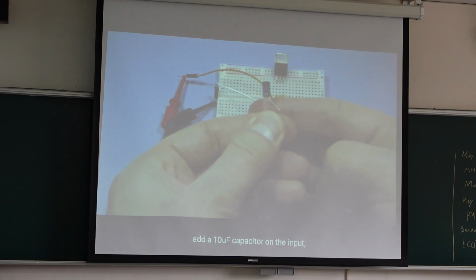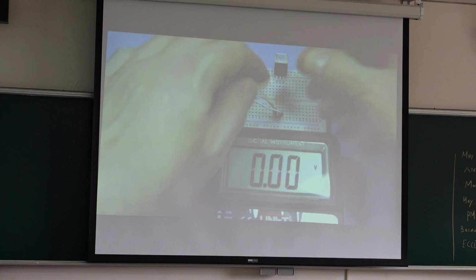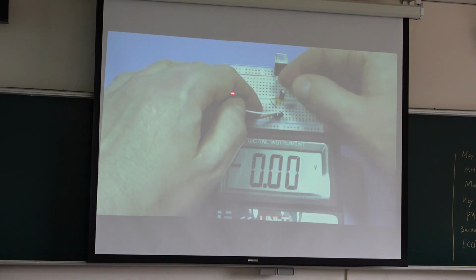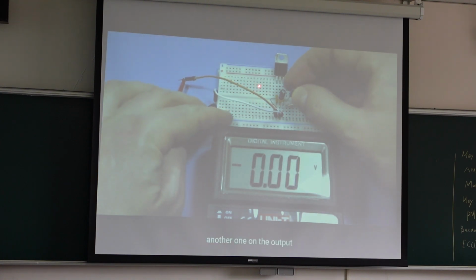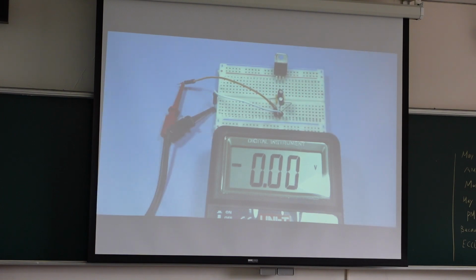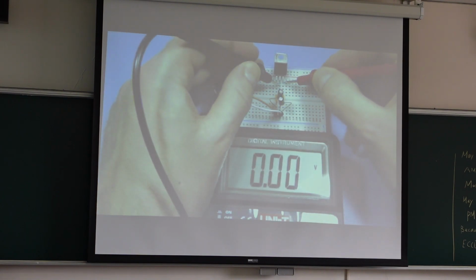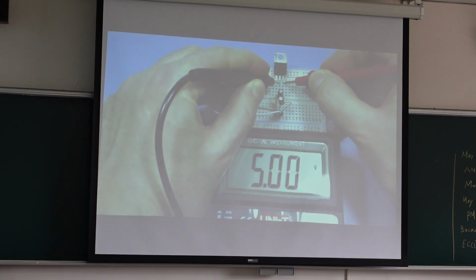Add a 10 microfarad capacitor on the input, and another one on the output as the output capacitor, and you get a steady 5 volts.